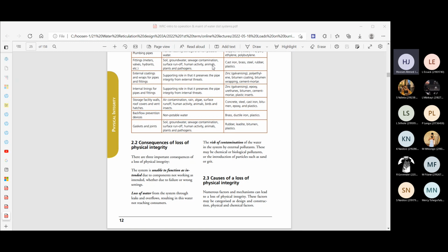In fact, just a follow up: when I talk of unit weight of the soil, it's actually not the undisturbed unit weight. It's the unit weight of the backfill soil that you are placing back over there. Thank you, sir. Okay. Any other queries?